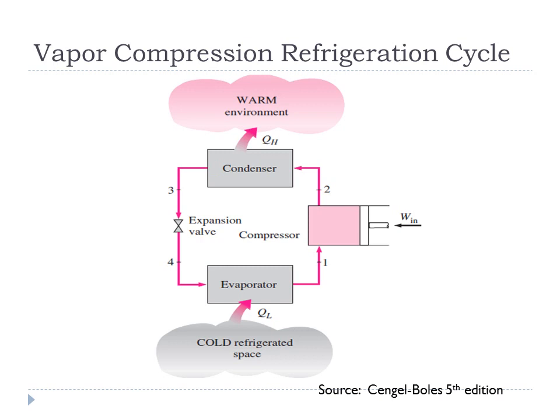So at state 3 we get saturated liquid of the refrigerant, and that is at high pressure. Since this heat rejection process in the condenser does not observe any pressure loss in ideal case, the process from 2 to 3 was a constant pressure heat rejection process. So at 3 the pressure is high, temperature is still higher.